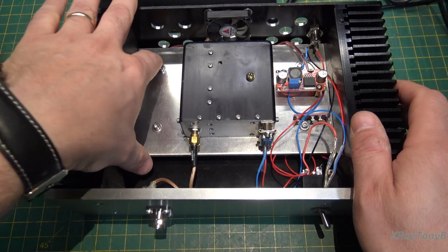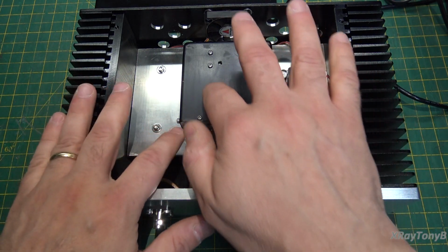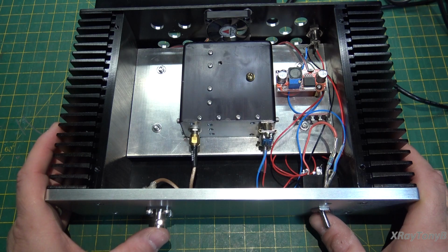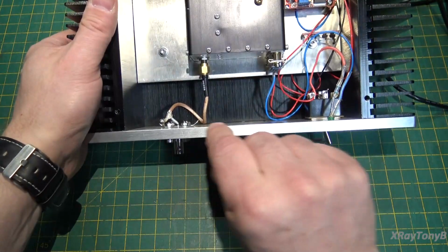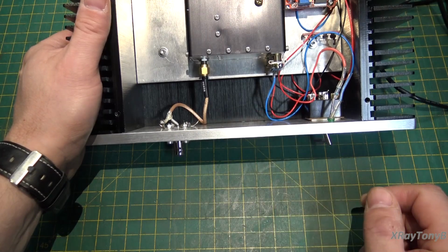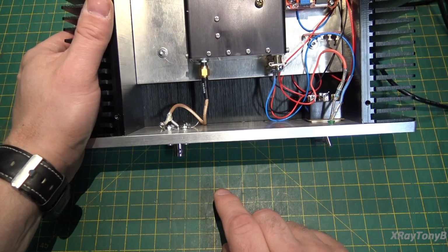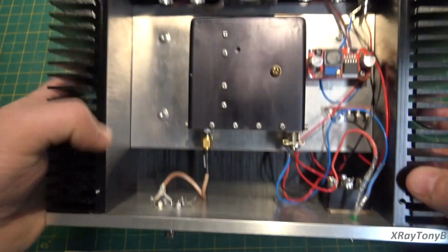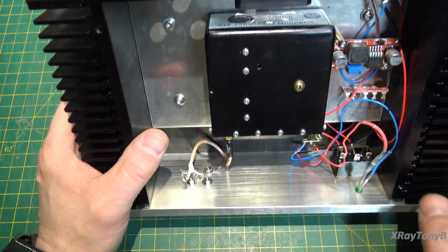So I have a piece of thick, quarter-inch thick aluminum stock that I used heatsink compound on, and I mounted this rubidium oscillator to that. I made up the cables here, and you can see how thick this metal is. It's very thick, like more than a centimeter thick, I'd say. So of course nothing fits chassis mount through it, so I had to use one of these flange mount connectors. And you can see I drilled through here down in the shop and mounted it.